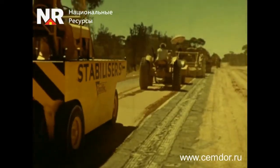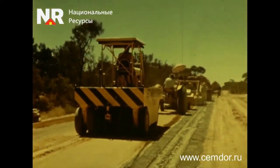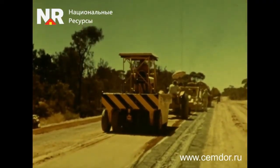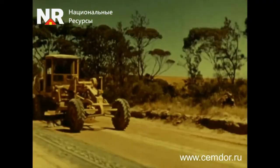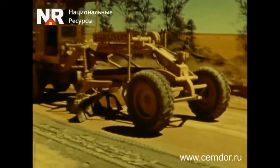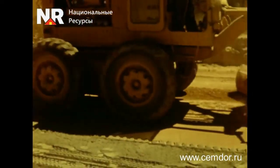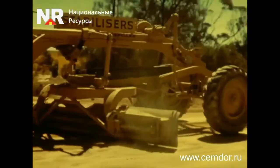Pneumatic rollers are usually used for final compaction. During compaction, the surface of the structural layer is graded with a grader to avoid irregularities that could later cause various types of defects. At the same time, the road surface is also cleared of foreign objects.